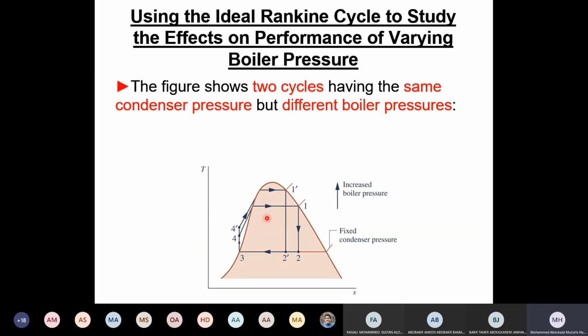Do not use the equation for the Otto cycle, but as far as you increase TH, the efficiency will improve. As far as you reduce it, the efficiency will decrease. So the efficiency will be improved, and the power we are not sure about, because we added this part, but we lost this part here. These are advantages, the efficiency improvement.